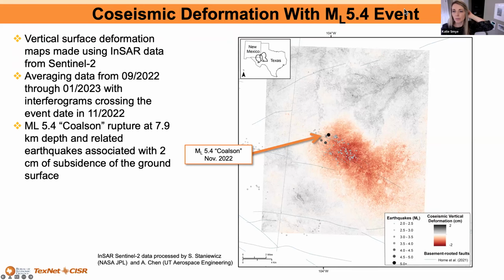What does the study provide on fault friction coefficients, and how well are the stress magnitudes constrained? Fault friction coefficients obviously is just such an area where we know so much less than we would like to know. We assume it to be 0.6, but through some of the work of Alan Morris and others, we do allow for that friction coefficient to vary a bit. What I would say from our work is that if our pore pressure model is accurate, sort of on the regional scale, these faults are likely much less stable than they are assumed to be with a friction coefficient of 0.6. So we would assume that these are probably much less stable.